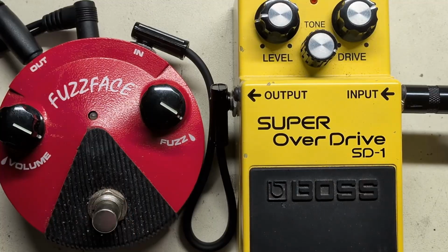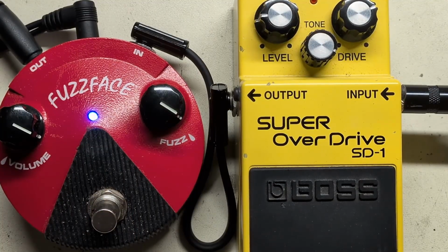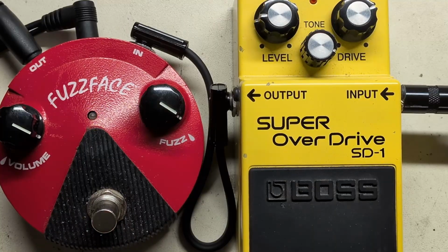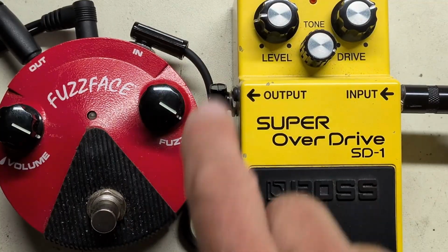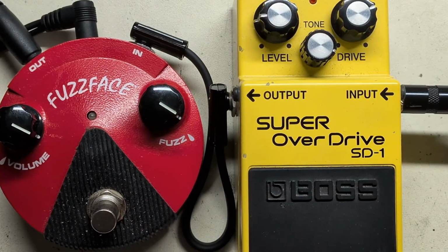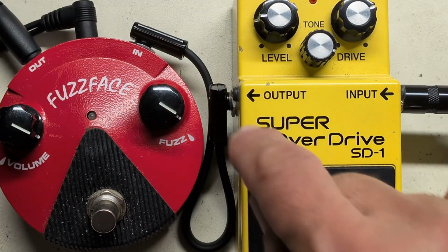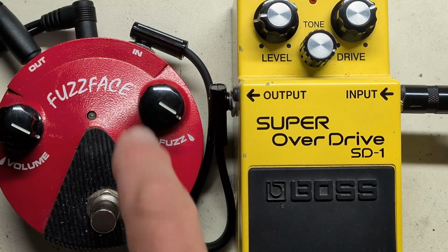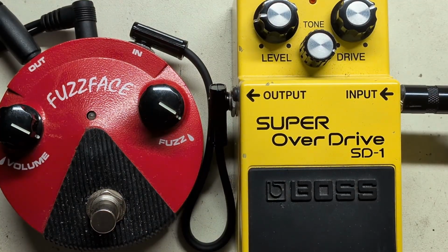and allow us to do all the cool things that we could do with the volume. And that's another thing. What you didn't see there is that I was actually turning the volume up and down and the signal was the same, and that's another effect of this buffer. So what we really want to do is bring some expression back into the signal path, so when we adjust the volume we can get the great tones that we expect out of the Fuzz Face.